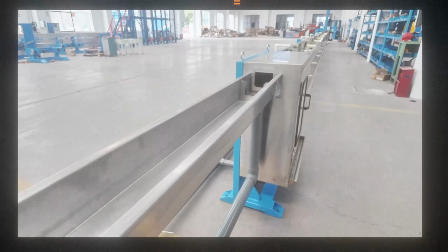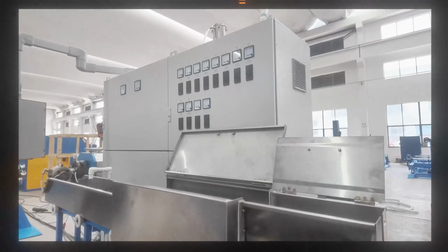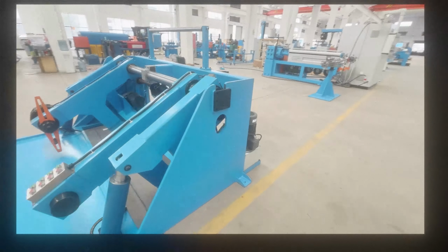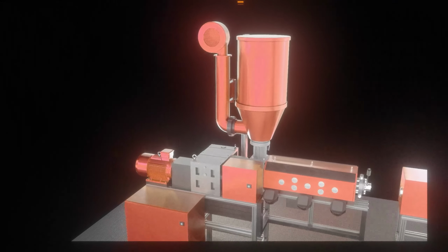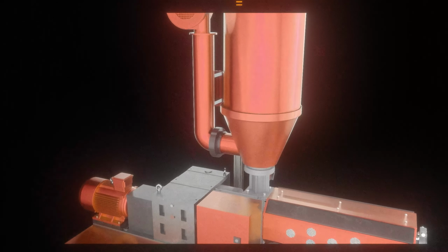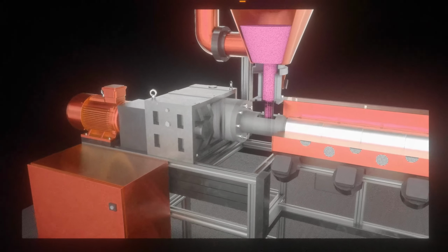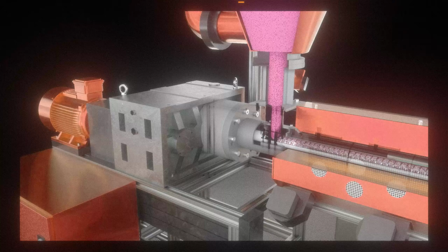Let's take a closer look at injection molding and extrusion. Extrusion: conversion of polypropylene into long products, rods. After synthesis, granules with low MFR are sent to extrusion lines. This process involves several stages. 1. Feeding into the extruder. Granules are poured into the hopper and fed into the screw system.